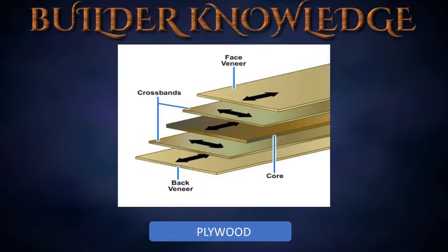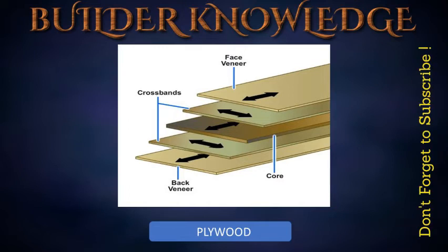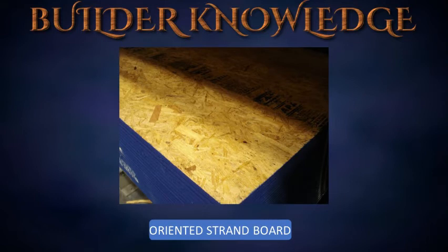Roof sheathing types. Plywood offers design flexibility, construction ease, economy, and durability. Oriented strand board, OSB. Wood strands bonded together with phenolic resin, place stamped face down with the rough side facing up.